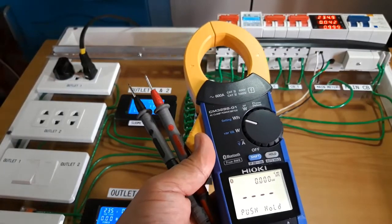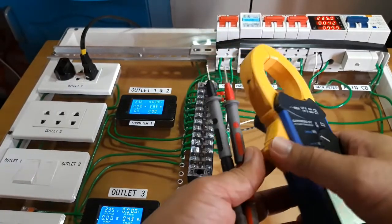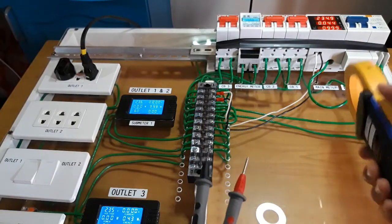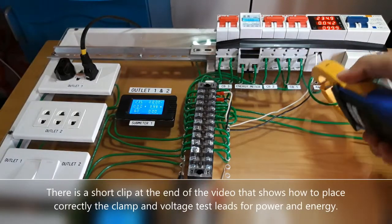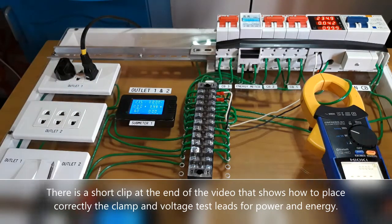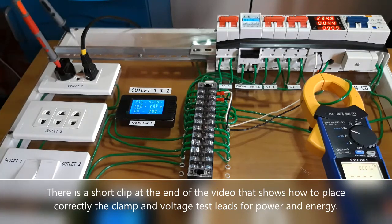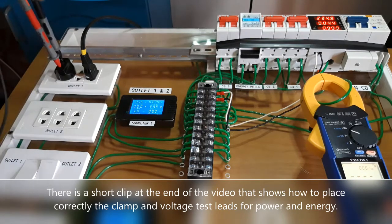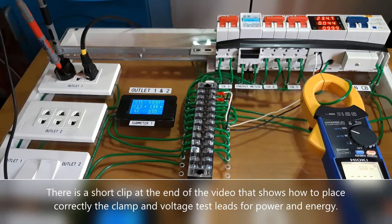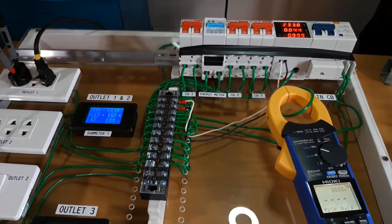Right now I'm going to set up the clamp meter for the measurement test. So I'm going to clamp the jaws of this clamp meter to the main line, which will measure, of course, the current going through the energy meter and to the load. And then I'm going to connect the voltage probe at these two measuring points for voltage, and we can begin the measurement.